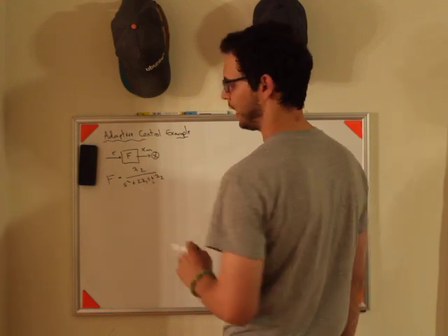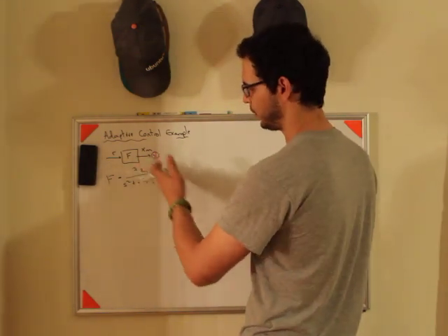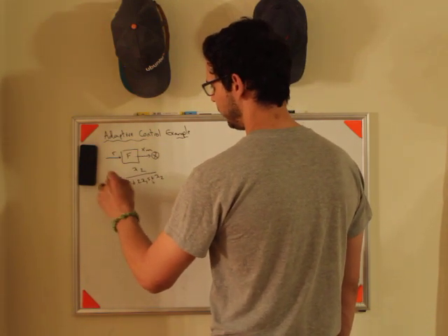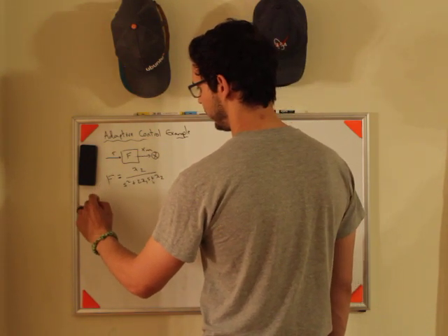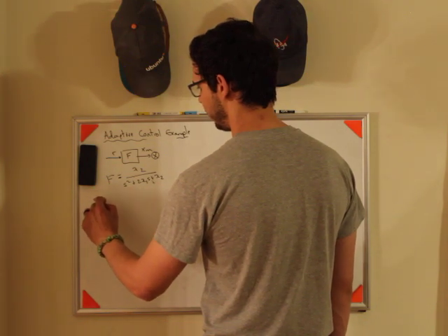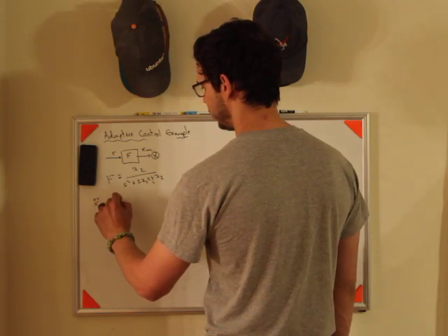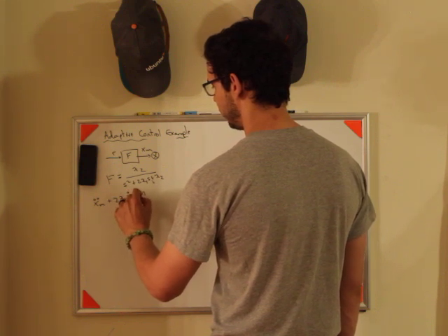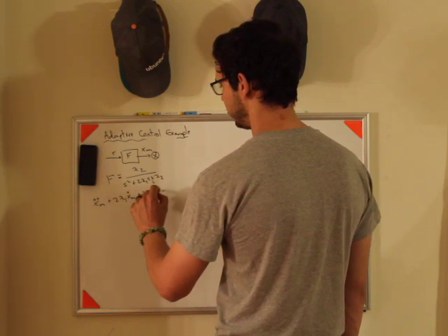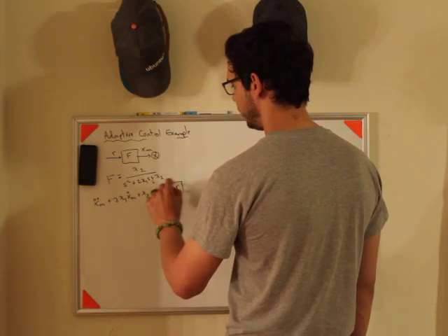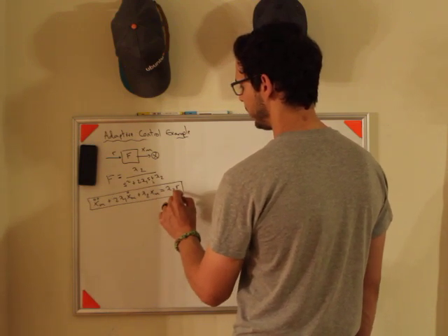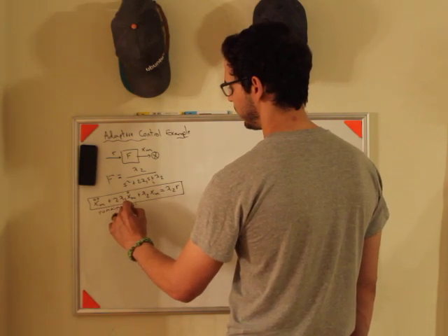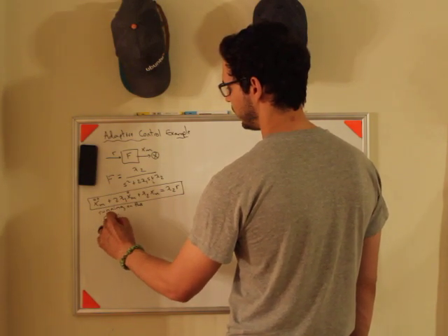You'll see I made the gain, the final value, equal to 1, so that the final value of x model is equal to r. If you do the inverse Laplace and cross multiply, you end up getting x model double dot plus 2 lambda 1 x model dot plus lambda 2 x model equals lambda 2 r. Those are your model dynamics. So this is running on the computer.